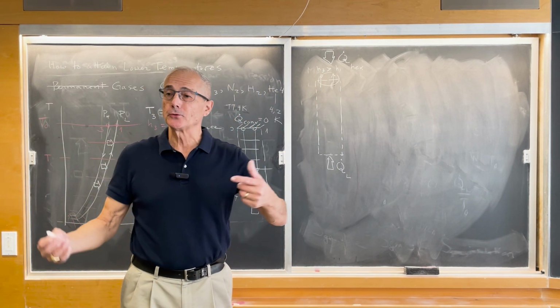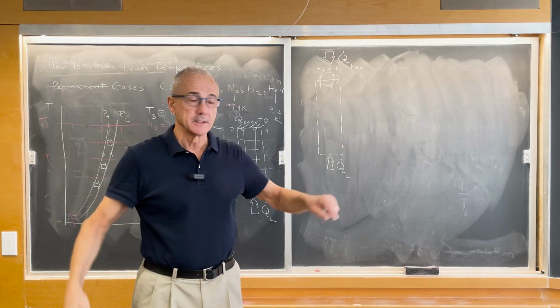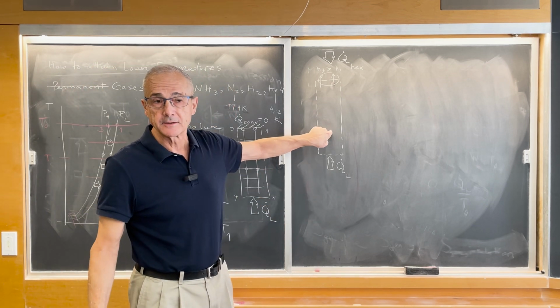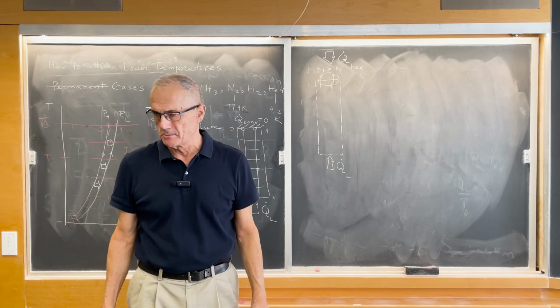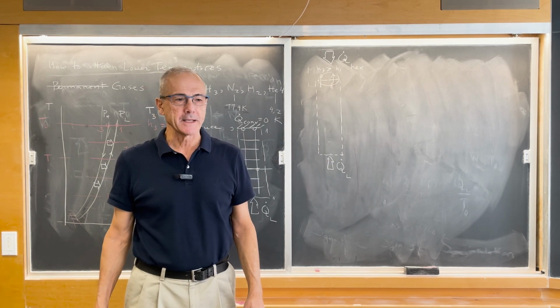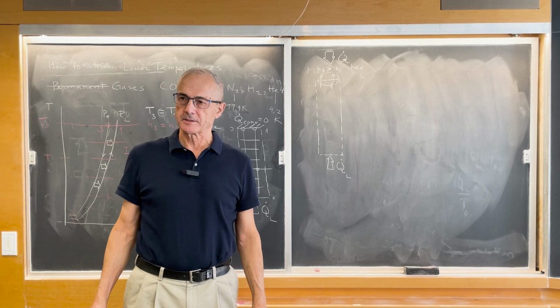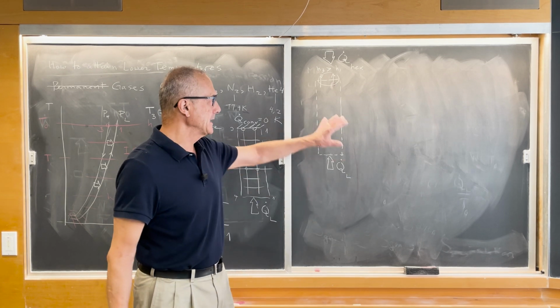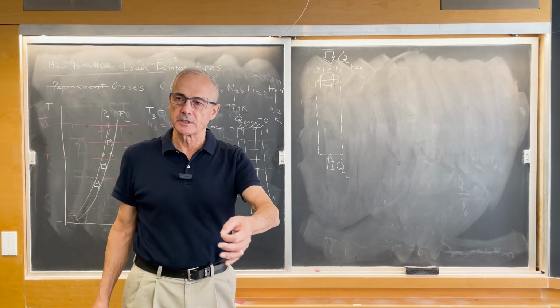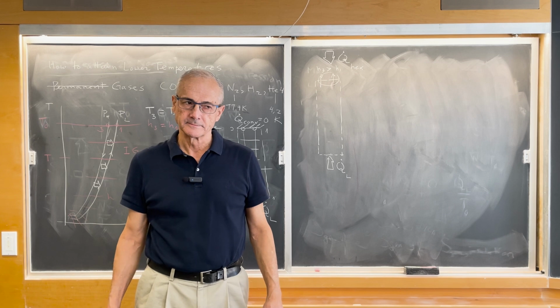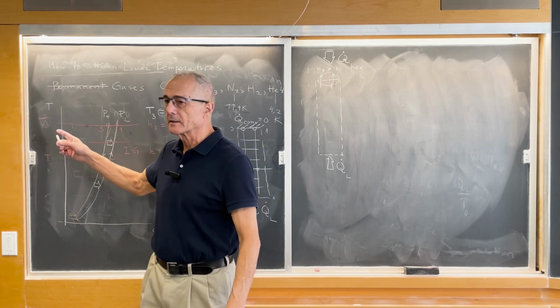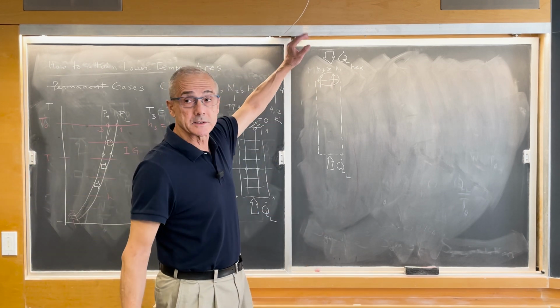And now you have two heat transfer rates entering the control volume with nowhere to go, meaning threatening the existence of the steady state. This is the kind of drawing that says this machine will not work, even though you are spending power outside this control volume.